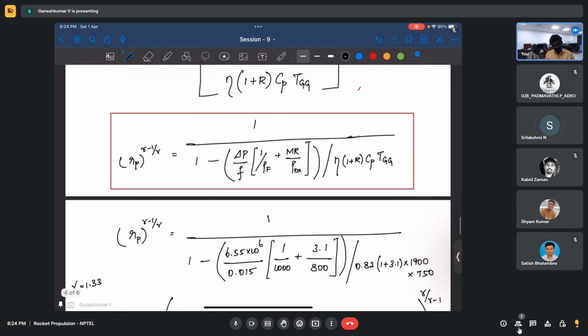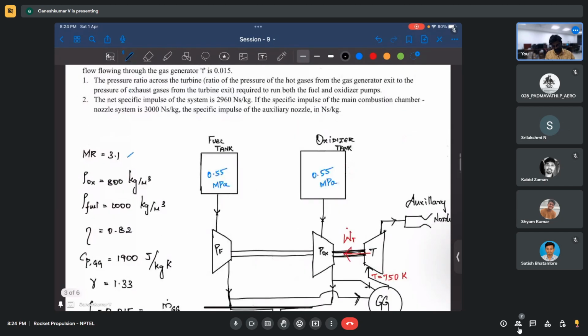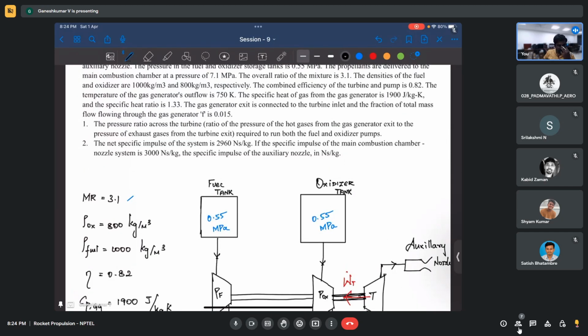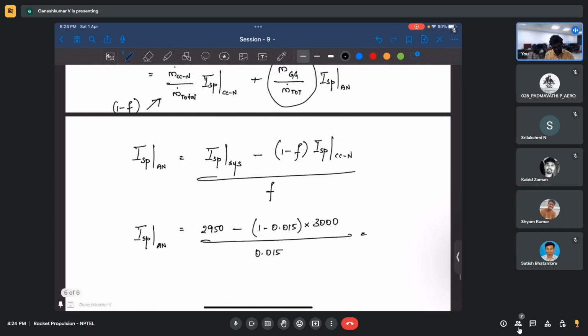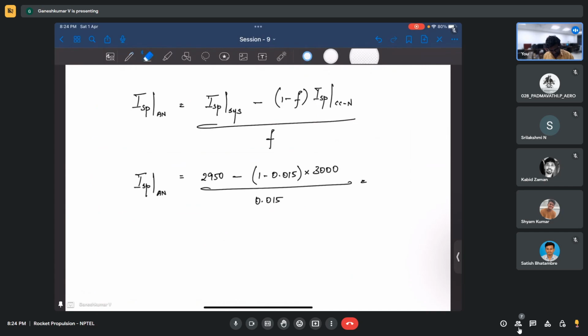I think there is a problem with the numbers I gave. Raise the specific impulse, it cannot reduce it. So it is. Oh, okay, okay. So it has to do with, this is 1 second. This is not 50. This is 60. Let me make this correction. So it does reduce the overall specific impulse. It's simply because you are dividing the mass flow rate.